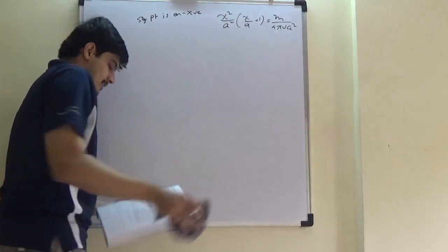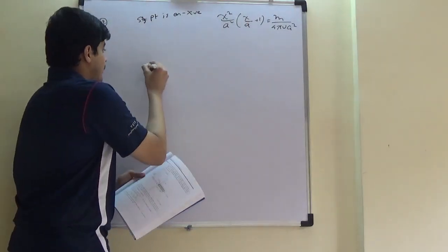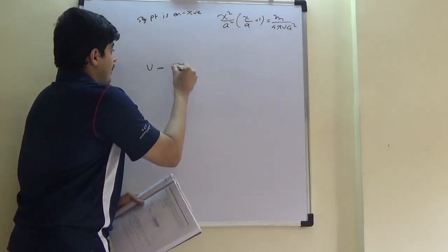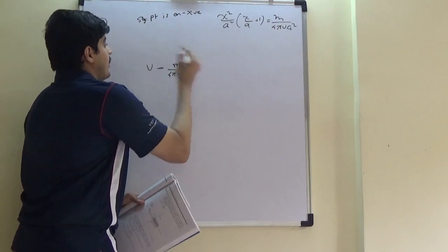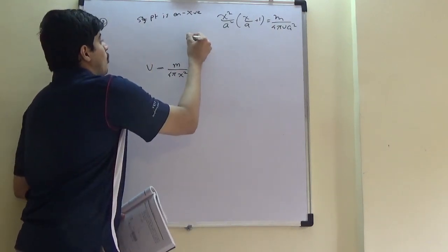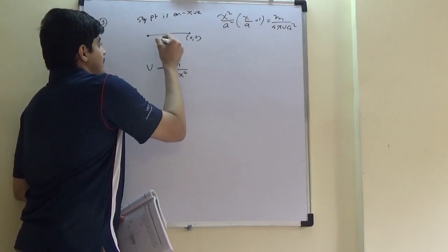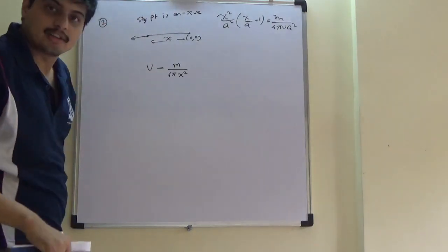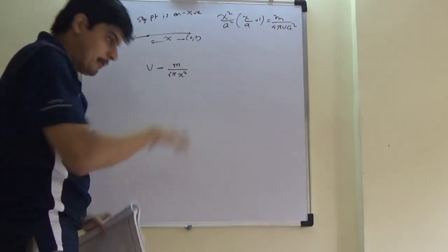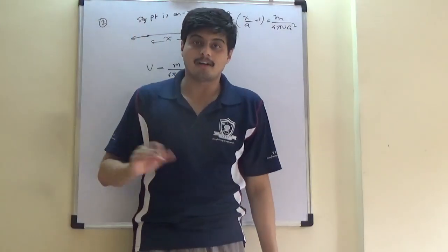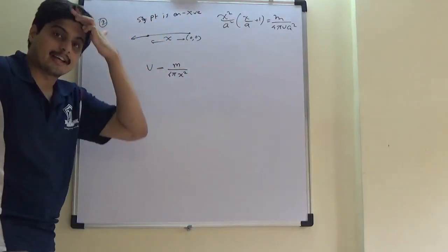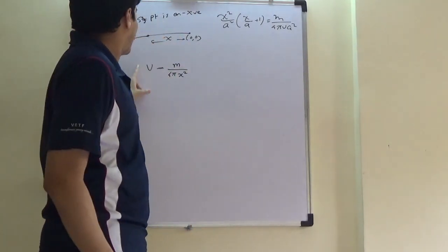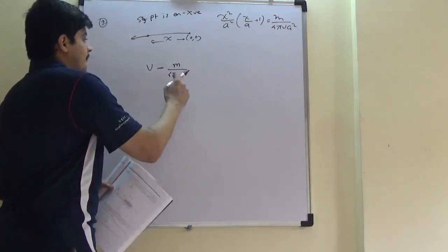We know very simply now that at a stagnation point, velocity u, right, minus m upon 4 pi x square, right? Now from the origin at a distance x, the source would provide this velocity. Now there is no y-directional component, we know already, because the symmetry of the problem dictates that it is mirror symmetric, and therefore the x-axis is the axis of stagnation. So I am reasoning that only this x-axis component is what matters.